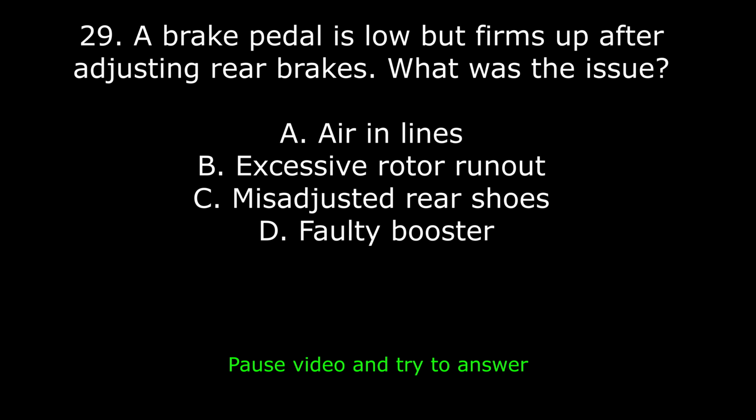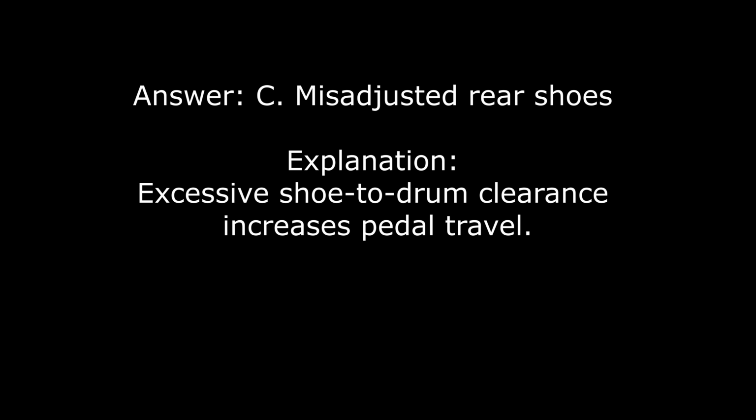29. A brake pedal is low but firms up after adjusting rear brakes. What was the issue? A. Air in lines. B. Excessive rotor runout. C. Misadjusted rear shoes. D. Faulty booster. Answer. C. Misadjusted rear shoes. Explanation. Excessive shoe-to-drum clearance increases pedal travel.